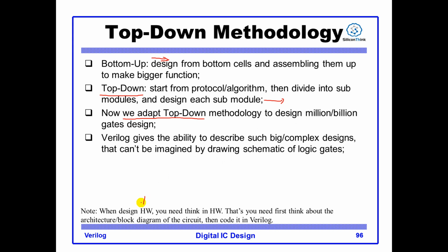And when you design hardware, you need to think hardware. That is, you have to first think out the architecture or block diagram of the circuit, then code it or describe it in Verilog. You can't do it in the inverse way. That is, when you have the requirement, you just code it in Verilog and let the tool think about the architecture for you, or let the synthesizer tool think about the architecture for you. This is totally wrong.